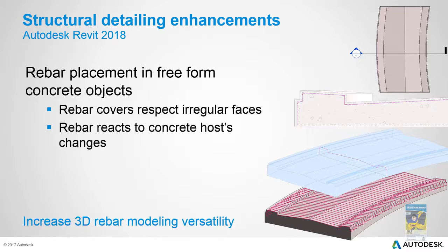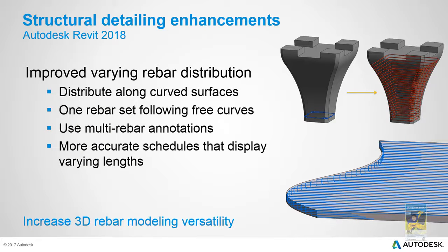In regards to Rebar, they have enhanced the software so that it can be placed a little bit better in freeform objects, and also respects the host if the host changes, as well as the rebar cover edging. They've also improved the variable rebar distribution feature so that it behaves a little bit better than prior. And obviously you can schedule that out if you need to, as well as annotate that information.